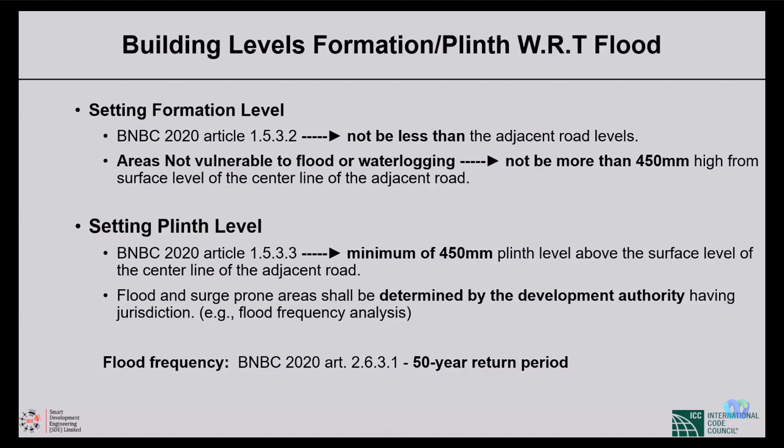Then the plinth levels, there are two notations. One is the surrounding level, and then the plinth level. You know my point? For the surrounding level, there are areas by plinth, and that sort of level, 45 centimeters, you have to raise from the formations. This is the minimum, they said. So these are the things you have to look at.